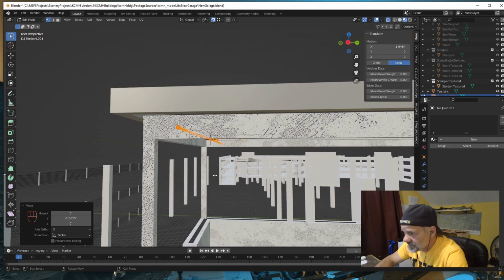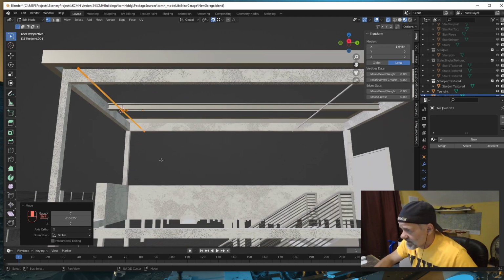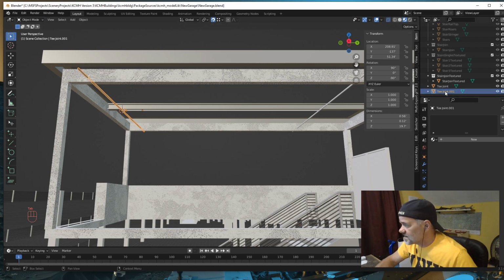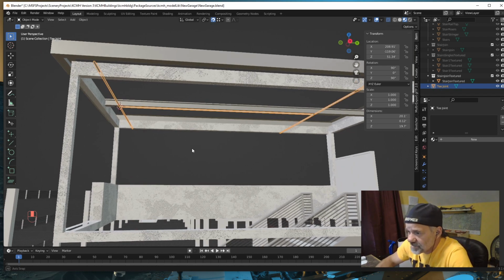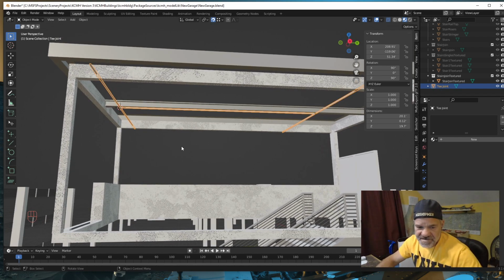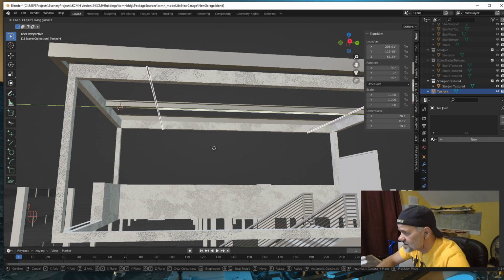Now these arms are a little too long. Plus, I need to take all of this and move it this way because it's closer to this end than this end. All right, the mirror is like this, but I can actually join these two T-joints. So get out of edit mode, select this T-joint, Shift this T-joint, and Control J, and now those conduit sets are one piece. Now I'm going to G, Y, and we're going to slide this down here.